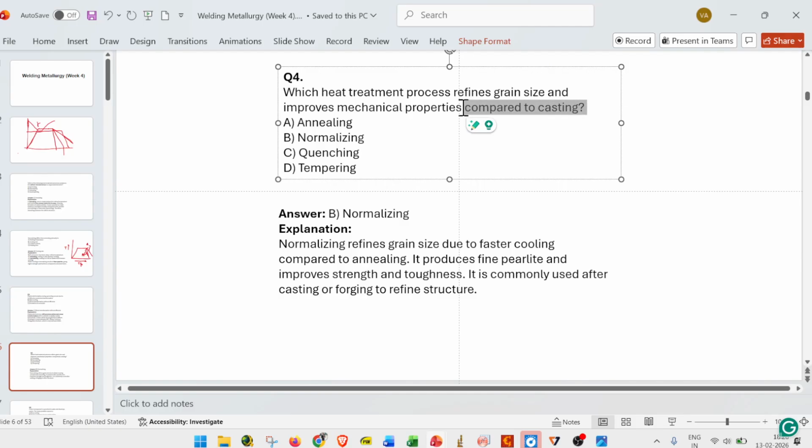So for mechanical properties, if we consider hardness, we will get more in the quenching case. In the case of casting and the remaining heat treatment processes like annealing and normalizing, in both cases we will see the formation of the pearlitic phase only. So we should consider only these two things. Tempering is used for surface hardening, where a harder phase, like a partially martensitic phase, forms on the surface and inside it will be the pearlitic phase. For that it will be tempering.